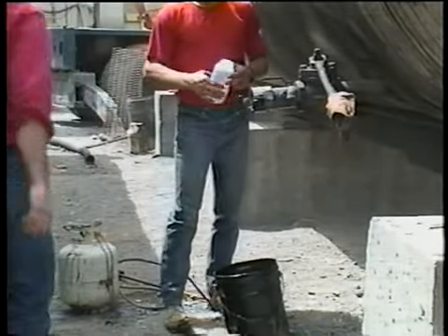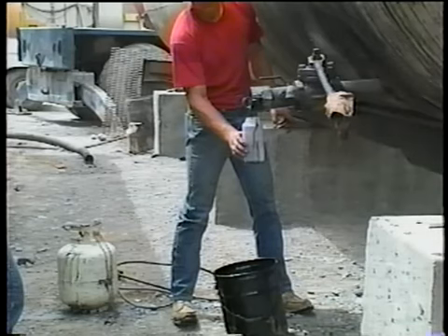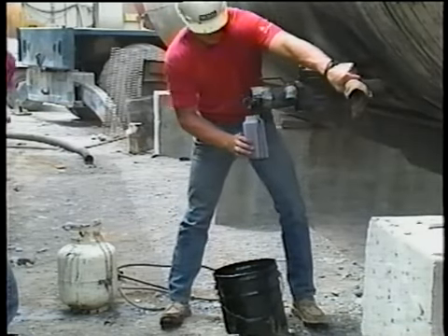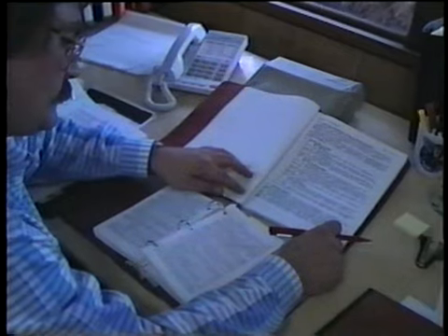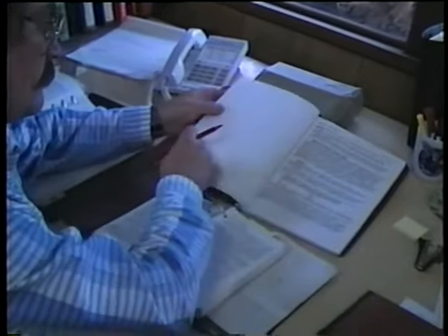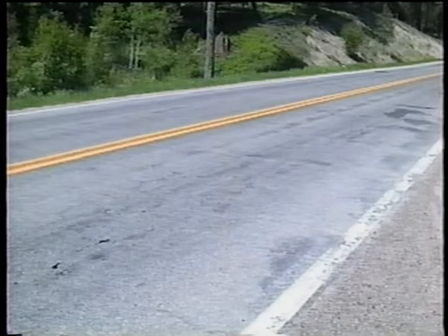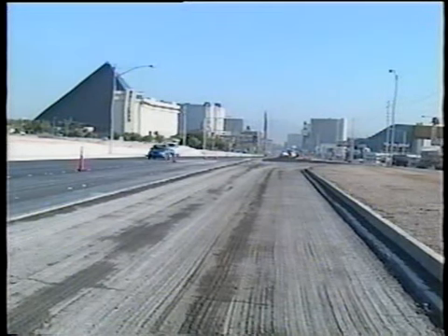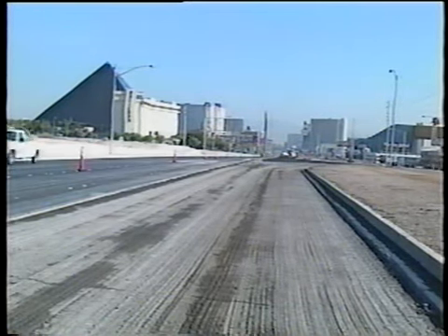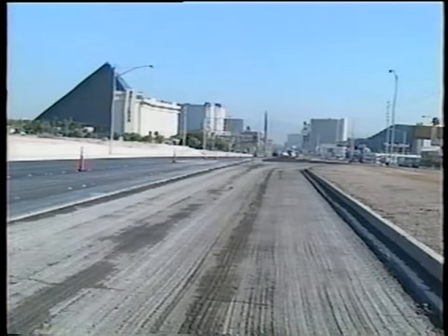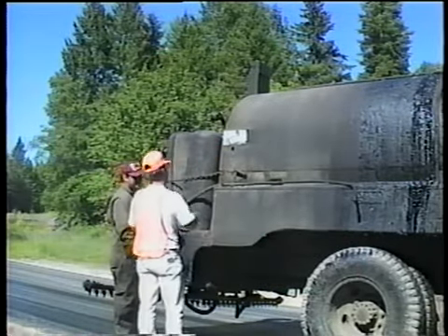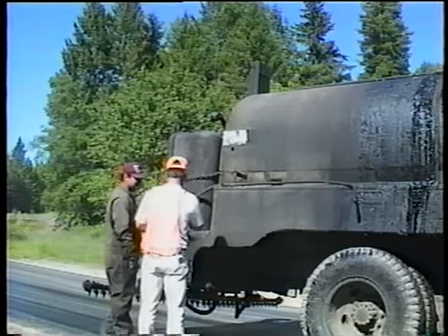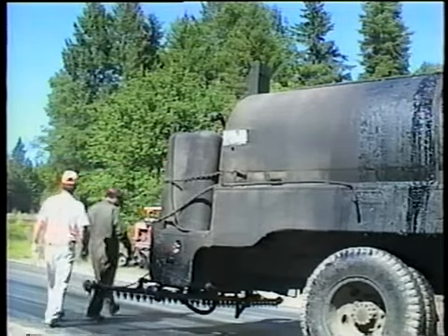As inspector, you may have to sample the tack. If so, be sure to follow your agency's procedures for collecting, documenting, and submitting the samples properly. Next, find the application rate for the tack coat in the contract documents. Many agencies will allow you to make small adjustments in the application rate depending on the condition of the surface. Basically, you'll always use more tack on old and milled surfaces than you will between new courses. Then, record the number of liters in the distributor so that later you can calculate the application rate. You'll also need this information for payment purposes.